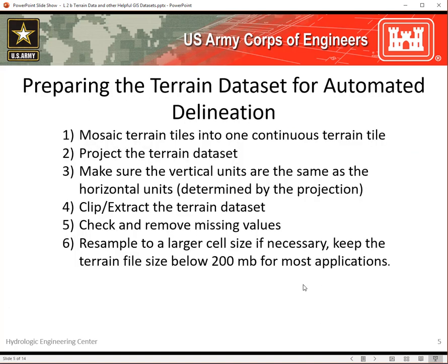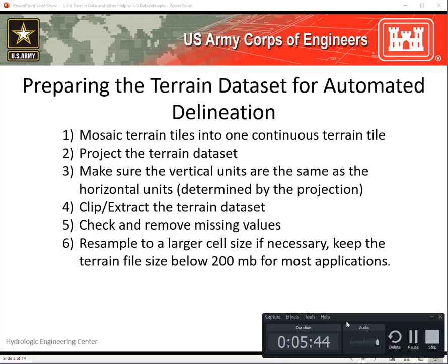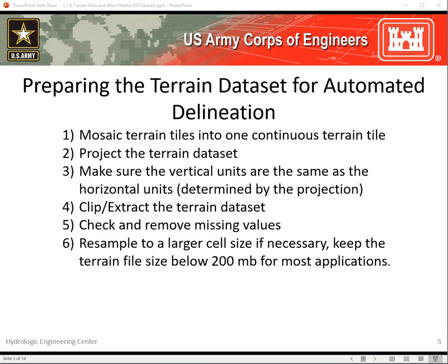All right, so let's talk through the steps that you need to follow in order to get the data ready to use within an HMS project. For many applications, especially those larger applications, the data set might be rather large when you download it from the USGS, and so you might get a couple of terrain tiles. In order to use the GIS delineation tools, you have to mosaic those multiple terrain tiles into one continuous